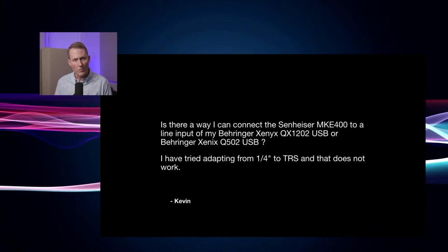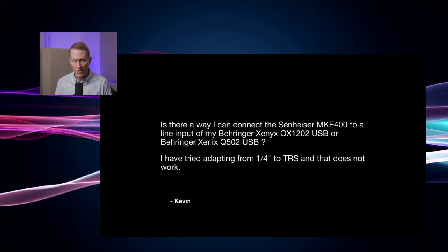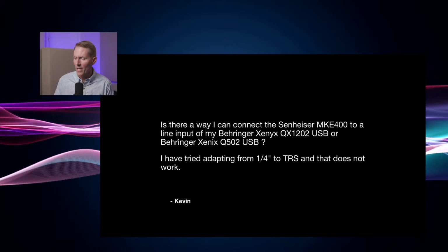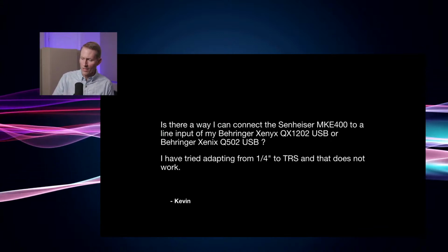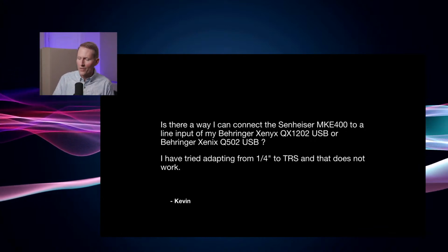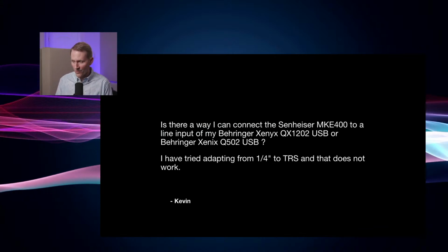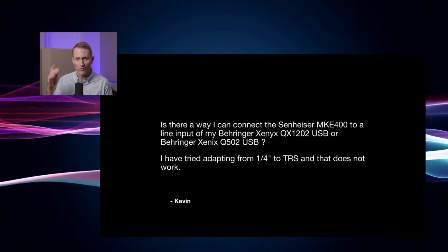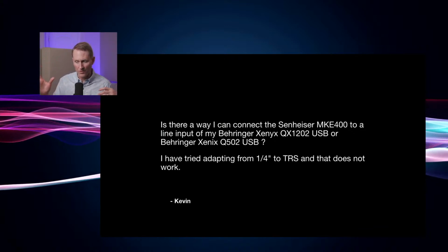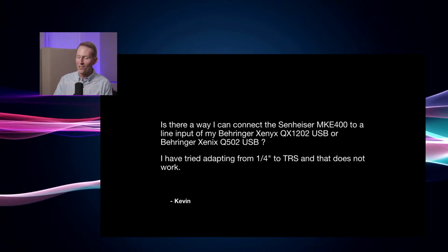So what you need to do is probably use an adapter like a Rode VXLR Plus or a Rode VXLR Pro. There are other companies that make those as well. In essence, the MKE400 also needs a power source. It needs plug-in power. Your mixers can only supply, if I am right about those mixers, phantom power, which is 48 volts usually, versus plug-in power, which is 3 to 5 volts. Pretty big difference in terms of electrical potential. So you don't want to feed phantom power to your MKE400.